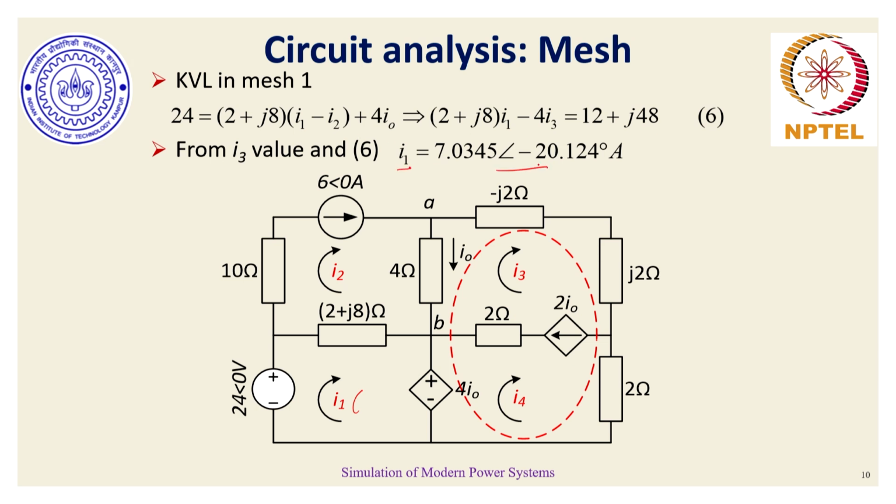We solve this and we get the I1 current. Since we have got all our individual currents, we can then find the corresponding voltage drops across these elements, find their corresponding power consumptions, and then verify that whatever power is being consumed, be it real or reactive power, in these different capacitors, inductors, RL load, resistive load, all that is coming from the combinations of the independent voltage source, independent current source, current dependent current source, and current dependent voltage source. So power checks or balances can be maintained or ensured.